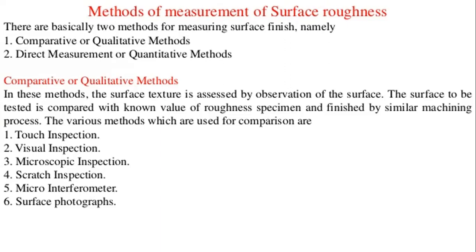The surface to be tested is compared with the known value of a roughness specimen. So the surface is tested against specimens of known roughness values, finished by similar machining processes.